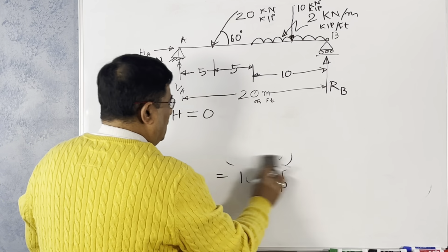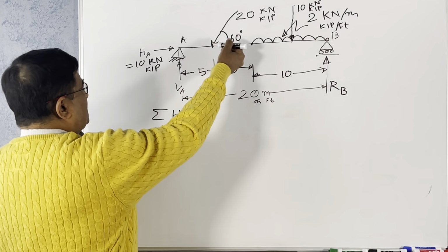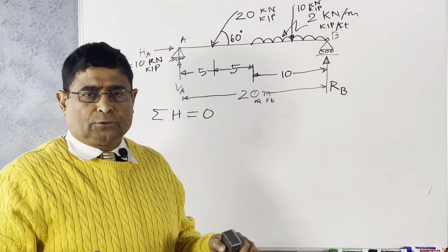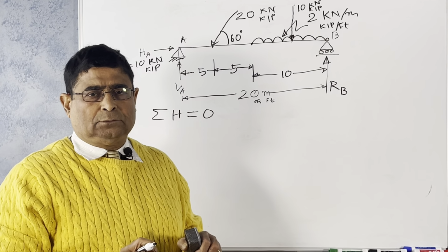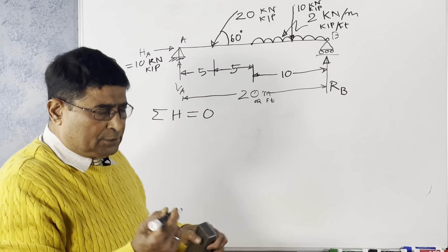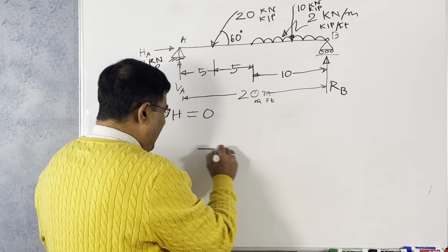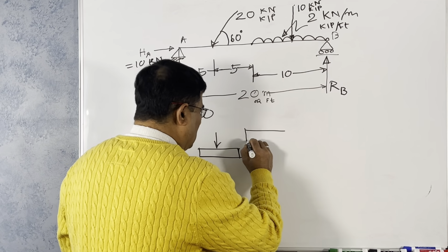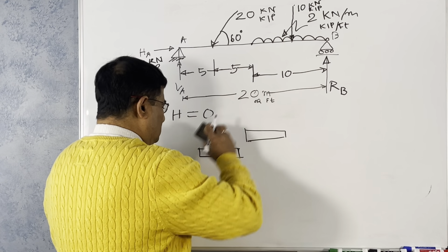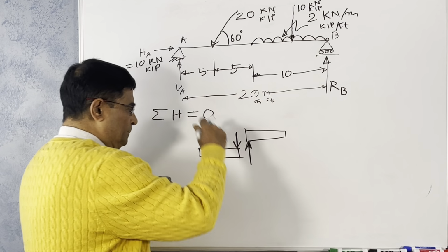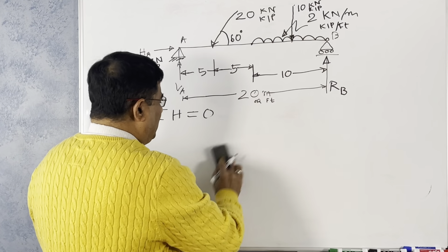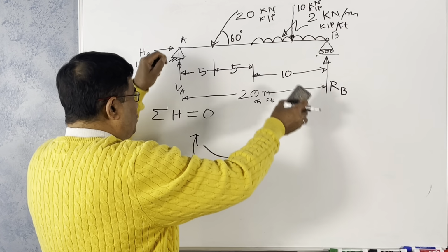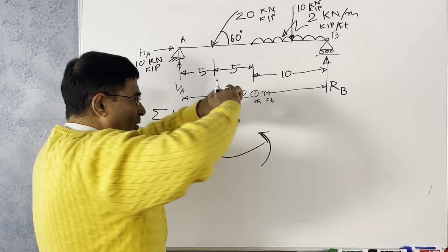Now this force is axial. So always remember, axial force doesn't cause any bending moment or shear force. The shear force is always transverse to the section, like that, shearing. And bending moment tries to bend. So the forces acting this way or that way try to bend, and the other just shears it.